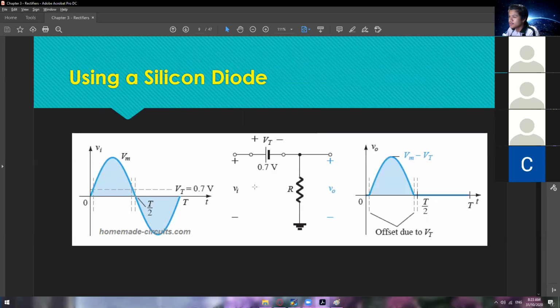Okay, so as you can see right here, we now have a voltage threshold. So same idea, you have a positive to positive, negative to negative. It's just that the diode now becomes a silicon diode. Of course, this will only conduct on the positive half cycle, but now in getting the V peak, you have to deduct the voltage threshold.